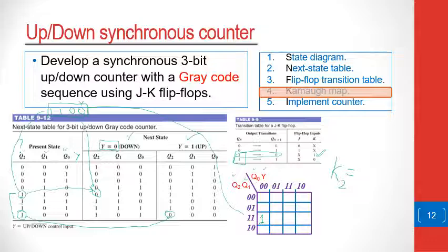And we can look at another instance, this second instance here, where this one transitions to a 0, which means the K map has to have a 1. In that case, we see that the present state is 1 0 0, but the Y input in this case, because it's up, is going to be 1. So this is the entry on the K map here. It's 1 0 0 1. So there's a 1 here as well.